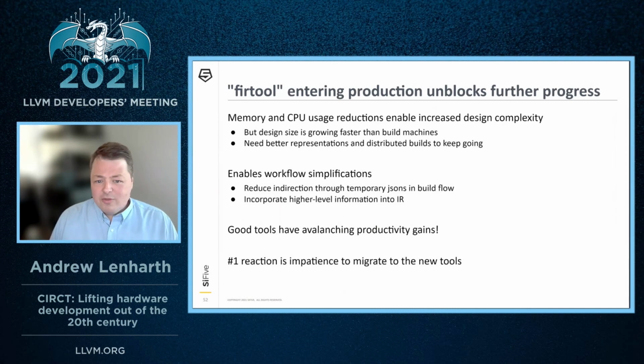One thing that's really nice is as we start getting more information properly structured in an IR, this allows us to start cleaning up all our build systems. Remember how I said there was all sorts of files for passing information between tools. A lot of those are an artifact of not being able to query Verilog, because Verilog is too nasty to parse. By the time you get there, you've lost some high-level stuff. So we can do a lot of cleanup there. And our main reaction so far is, when can we get this, and what else can you do? So for what else you can do, I'll turn it back to Chris.